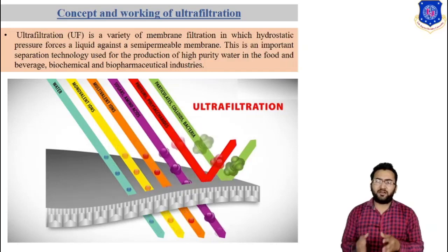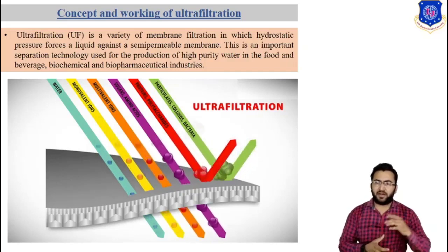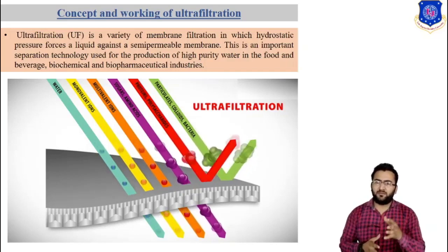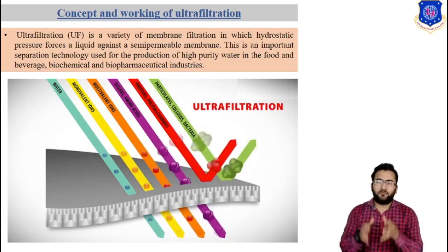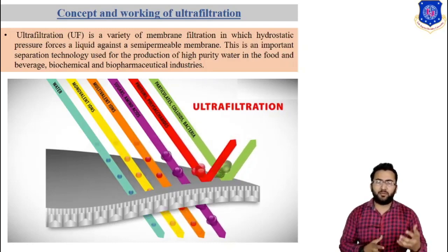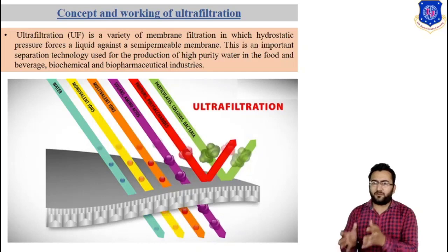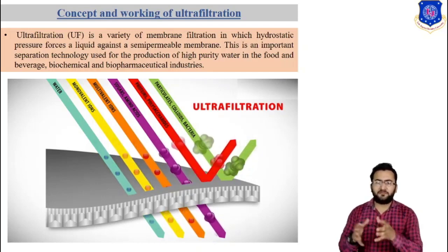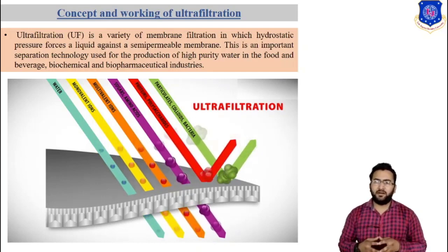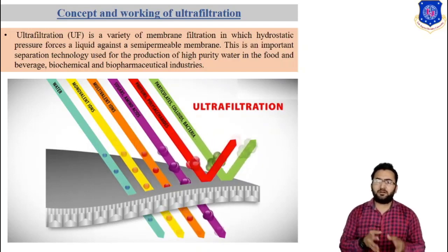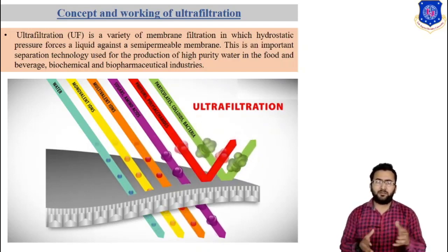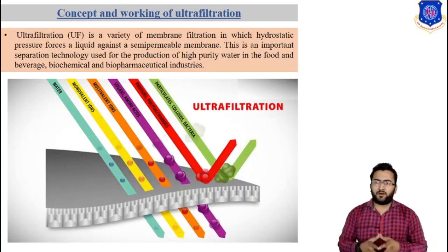Since fouling is a major problem in ultrafiltration and membrane separation processes, hydrophilic membranes generally foul less rapidly. There is a competition between the truly stable hydrophobic membranes and the less fouling-prone hydrophilic ones. Recently, thin film composite ultrafiltration membranes have come to market for high purity water applications.